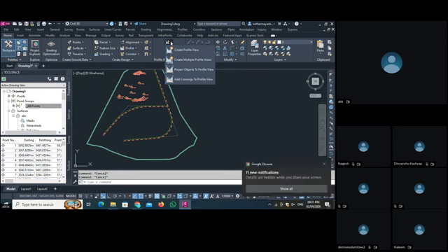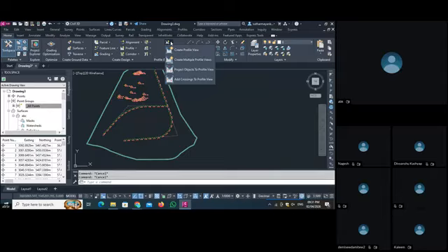Make sure of one thing, on a crest curve there is always a problem of visibility. You can't see the vehicle ahead clearly on the top surface, because the crest curve starts from the bottom, then goes up and then goes down. It is an inverse U shape, not a U shape, inverse U. Then the second one is a sag curve. A sag curve is in a U shape.